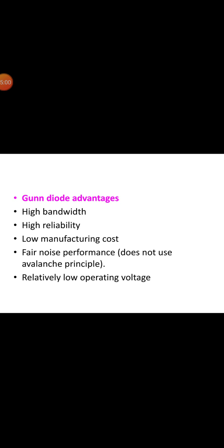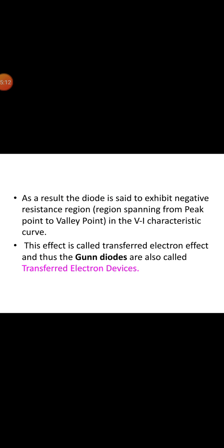can be represented with resistance, inductance, and parasitic inductance and capacitance. Where RS is the total resistance of leads, ohmic contacts, and bulk resistance of the diode, LP is the package inductance, CP is the package capacitance, RJ is the diode resistance, and CJ is the diode capacitance.